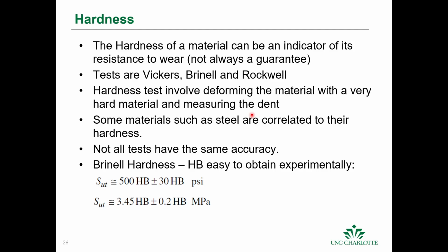They all involve the same approach, where you basically hit the material with something that's very, very hard, some stylus, and you look at the dent that the stylus leaves in the material under that load. And since you know the load that you're applying, you can look at the dent and get an estimate of the hardness. They don't all have the same accuracy. It's actually not very easy to go from one hardness to another. We'll show you a table of how you do that.